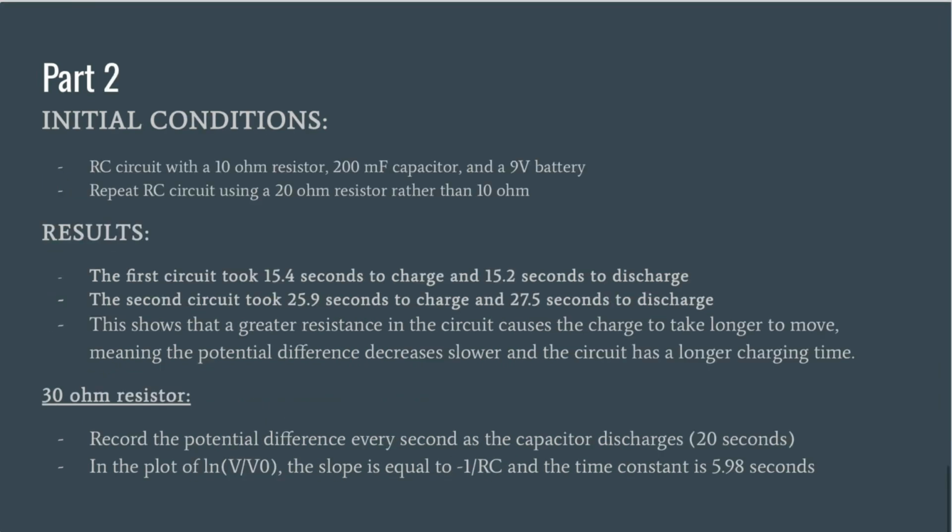Now looking at Part 2, the first simulation is an RC circuit with a 10 ohm resistor, a 200 microfarad capacitor, and a 9-volt battery. This circuit took 15.4 seconds to charge and 15.2 seconds to discharge.